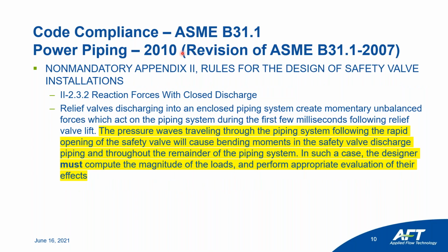Continuing with B31.1, the non-mandatory Appendix 2, rules for design of safety valve installation. This Appendix 2 addresses two types of discharges for relief valve. One is for relieving to atmosphere, an open system, and in that case, it has very good guidance on how to calculate the reaction forces. So that's why we're not going to touch them, but still you can use xStream to calculate those reaction forces when a relief valve discharges to the atmosphere.